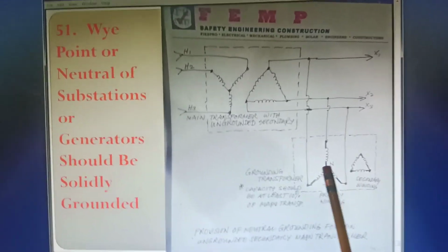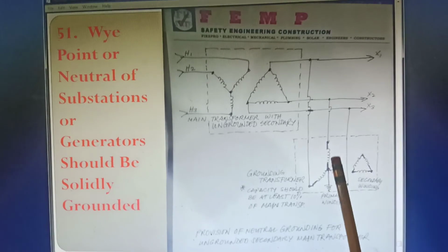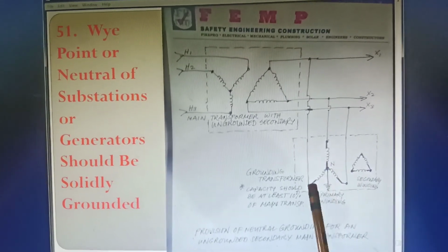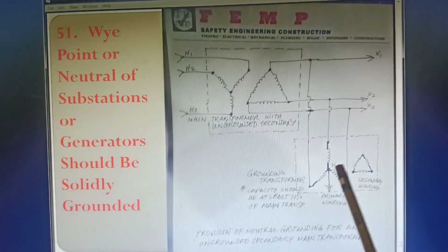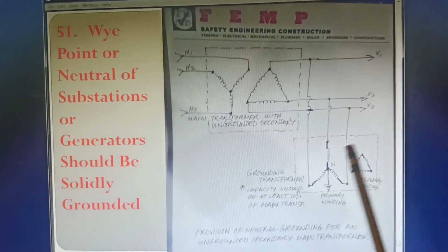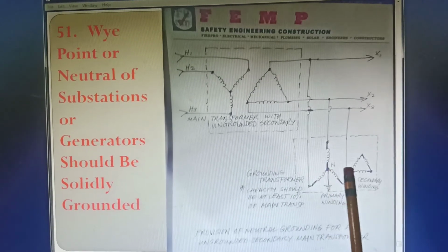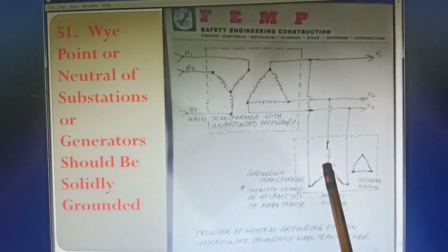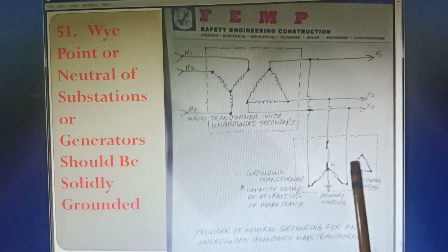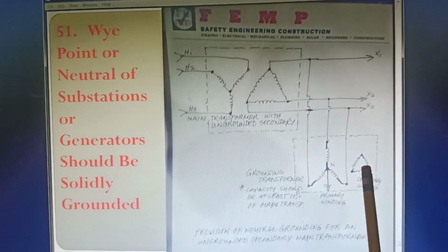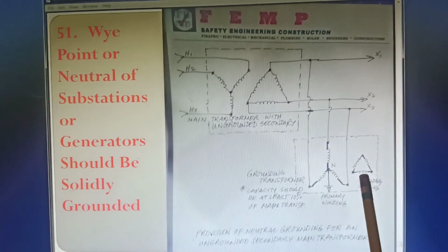Okay, in the absence of a three-phase grounding transformer like this one, you could use 3 single-phase transformers. In the case, like I said, 100 kVA is required, you should use at least 3 units of 37.5 kVA step-down distribution type transformers, with the primary connected in Y and the secondary connected in delta.